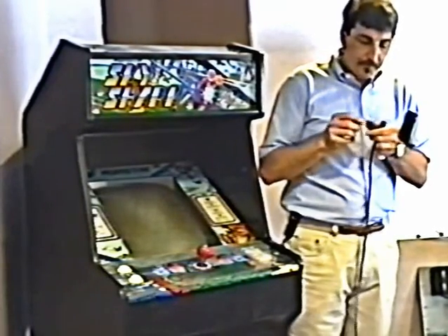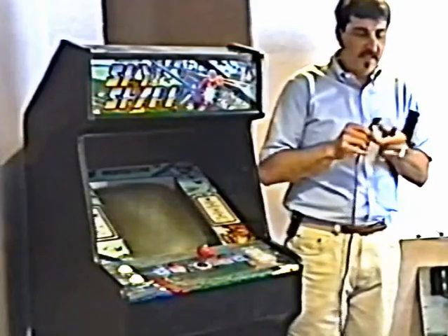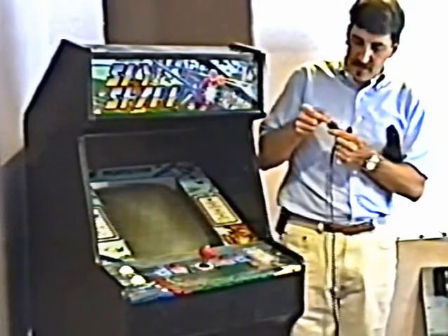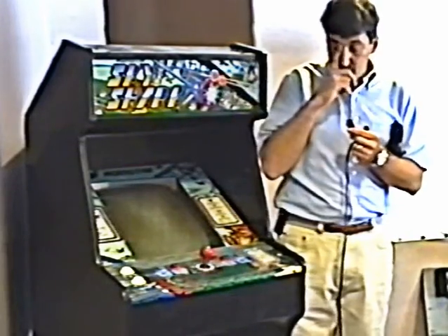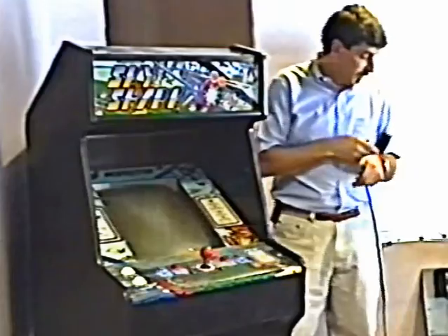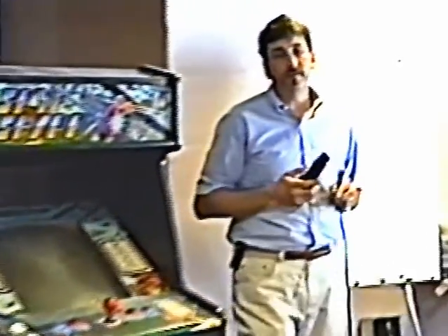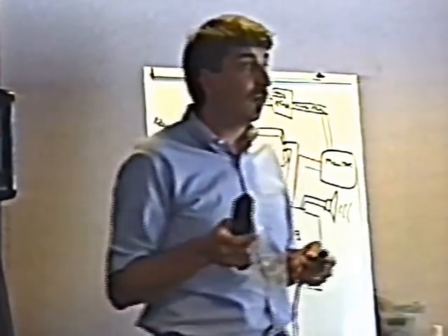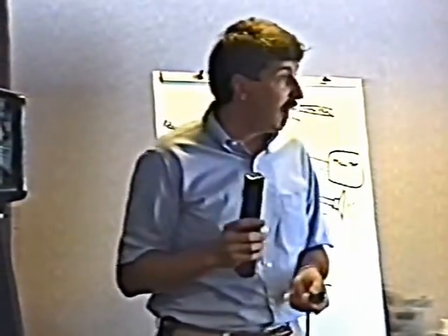Number two, the most common thing is this is in the wall, the game gets pushed up against it, it whacks the thing, and the little blades here are loose. And that's what's wrong in this case. Now, here's what I do to troubleshoot it. If I have a choice of two different ways to troubleshoot something, with the power on or power off, I always do it with the power off.